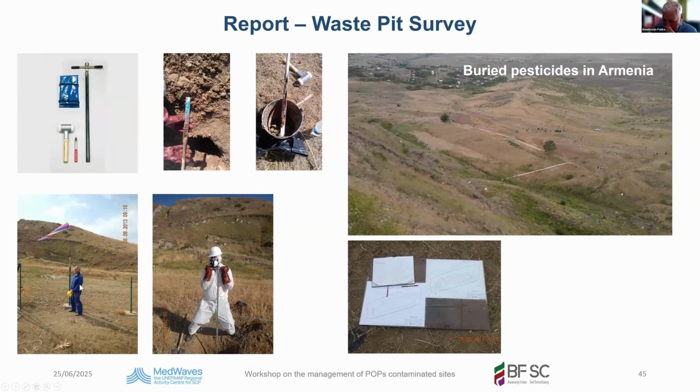If you stand upwind, in the direction of where the wind is coming from, you have not the risk of being exposed to dust coming from your bore cuttings. So therefore this wind sock is installed to know where you have to stand when you are examining your soil cuttings. And here is my colleague: half face mask, helmet, gloves, Tyvek, boots.